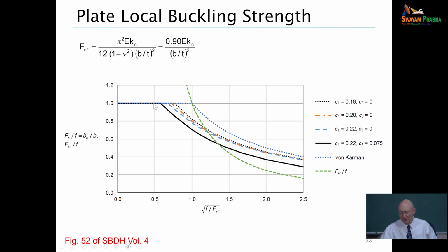Then there's one last curve here, that's the black curve, and that shows up only in the bridge standard in the US. And quite frankly, the black curve is something where, in developing provisions for being able to design massive longitudinally stiffened boxes and things of that sort, we're relying on finite elements for understanding what we were dealing with, not really a chance to do experimental testing on a massive box.